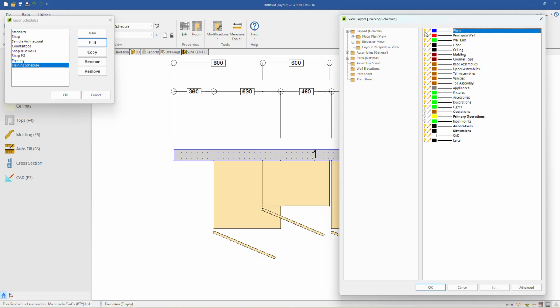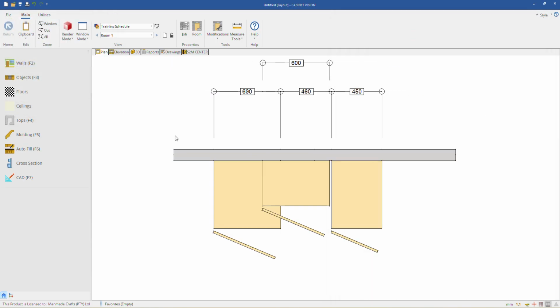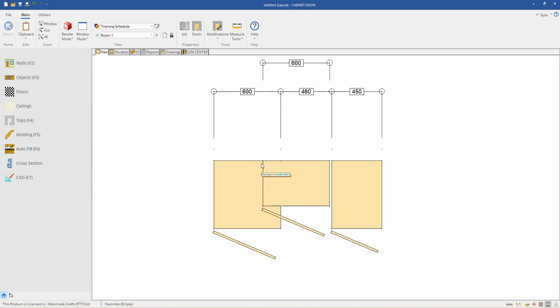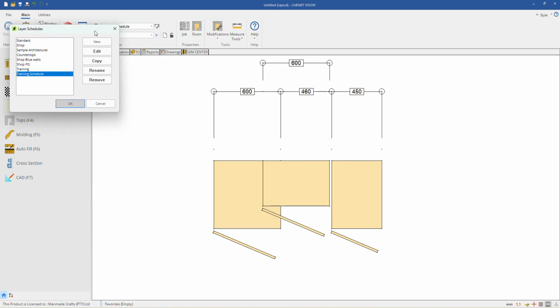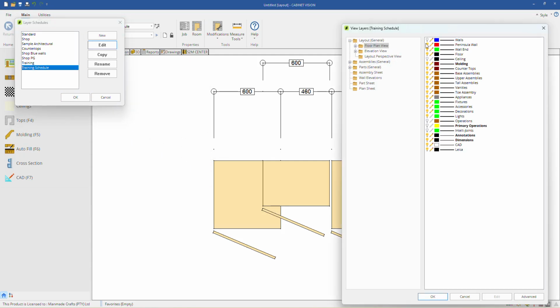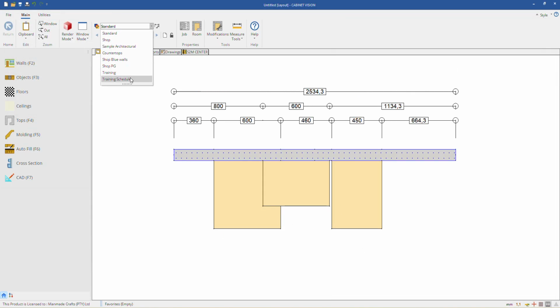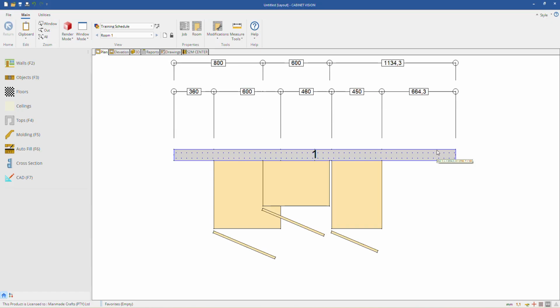So if I switch my walls off here, I say okay. Gone is my wall. So that just switches the view for it off. It's still there, I just no longer see it. If I switch that little globe on again and refresh it, there's my wall back. So that little globe on all of your different viewpoints controls if it sees it.